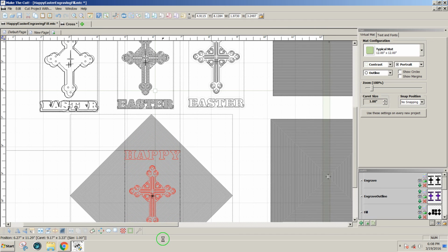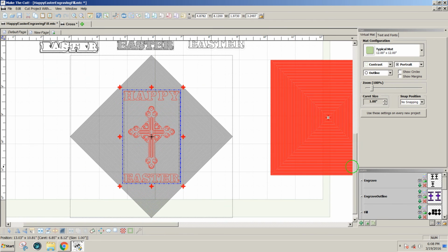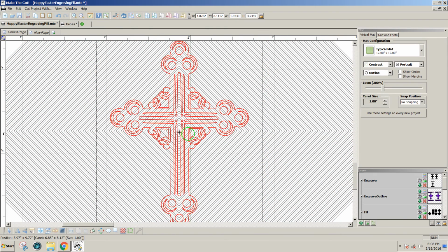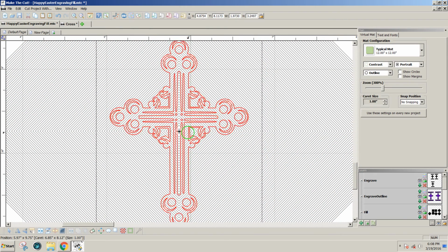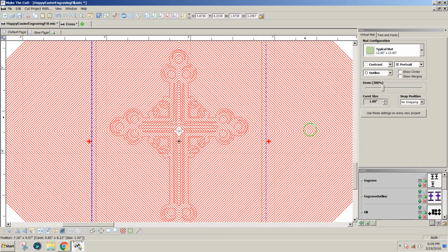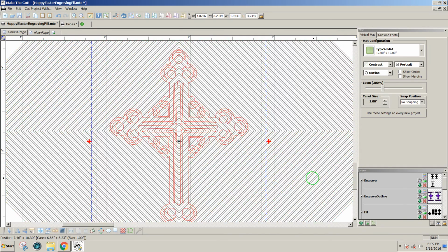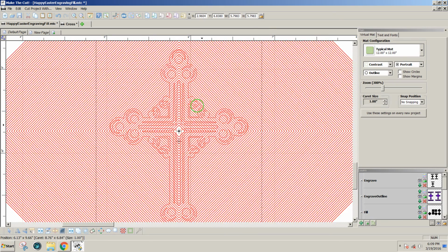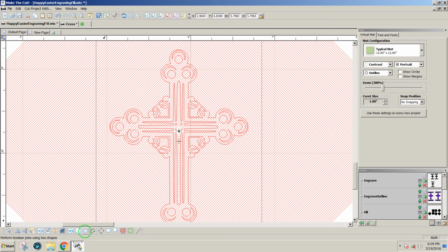What I want to do is put the center of that cross on the center of my design. I'll zoom in really close here, and I would normally use stack. That would put the little plus sign stacking on each other, but in this case the length and the width are a little different, so I want to line up the design and the cross with the position in my fill that is center. Now, holding the Shift key, I'm going to click on the fill, so I have both selected. So I'm working with two designs, and I'm going to click on Boolean Join.